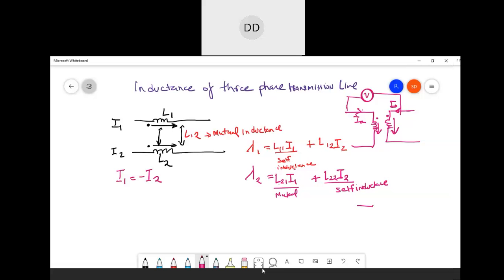If I'm joining two inductances, and there's one more inductance over here, and I'm joining a voltmeter over here, this is basically one type of polarity. Now if it was in the reverse direction, if I put a dot over here, what would it read? In this scenario I1 would be equal to minus I2.